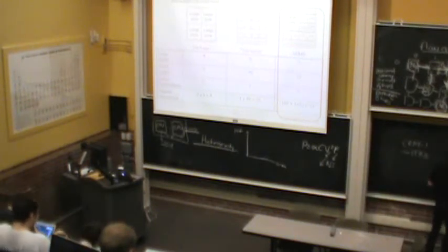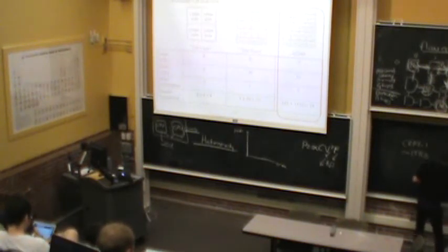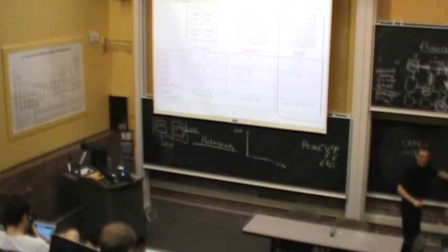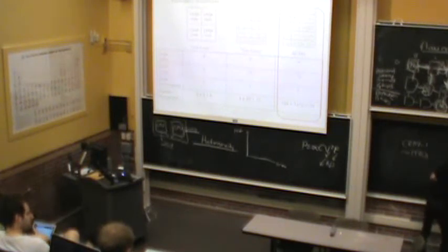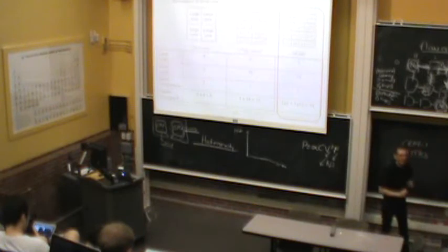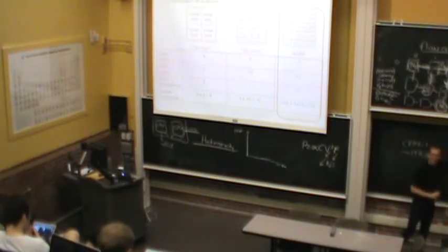It did have a vector unit, and it did have a scalar unit. The scalar unit was the fastest scalar unit of its time. Right? The vector unit, good for SIMD, data parallel operations. The scalar unit, good for serial code portions. Make sense? It's a heterogeneous processor.